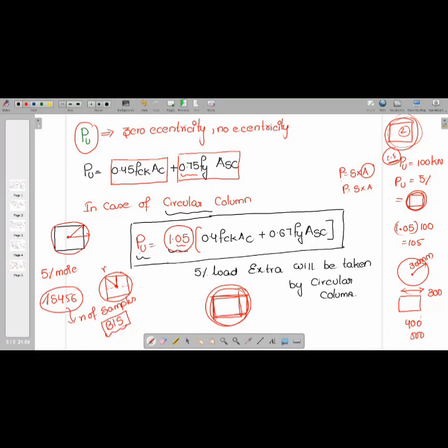The reason for a circular column is it takes more load. If you are supporting a beam on a column, the surface area of the circle will also be more. That is the reason if you see huge spans, home theaters, cinema theaters, mosque, church, temple, or anywhere where public gathering is there, you will observe circular columns. But in your buildings, like in your home, they will be rectangular columns. If the loads are heavy, we go with the circular column. Agree? Yes, sir.